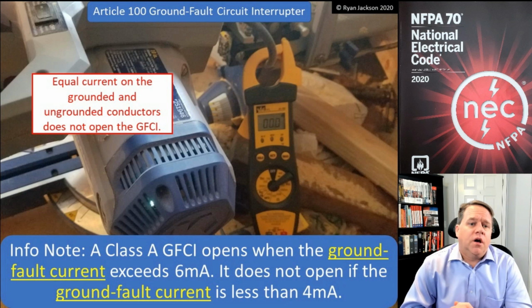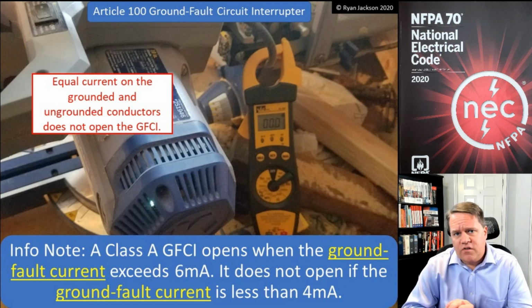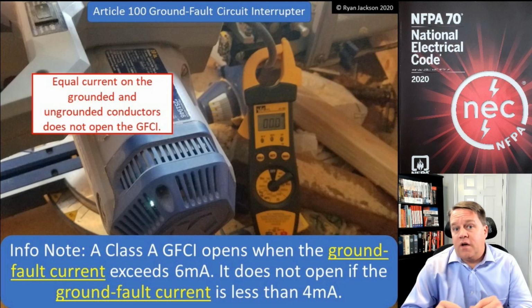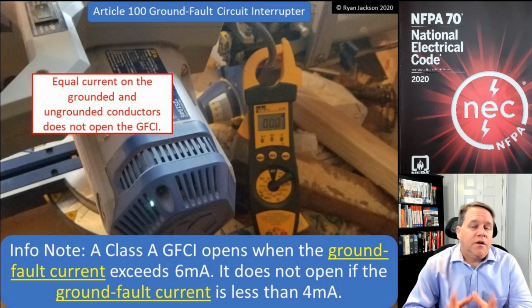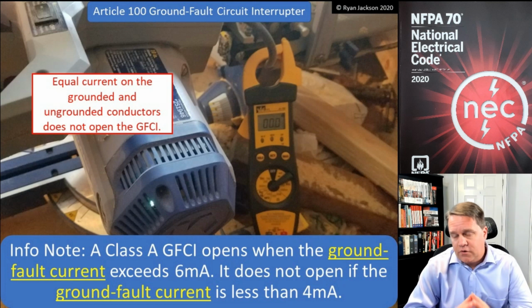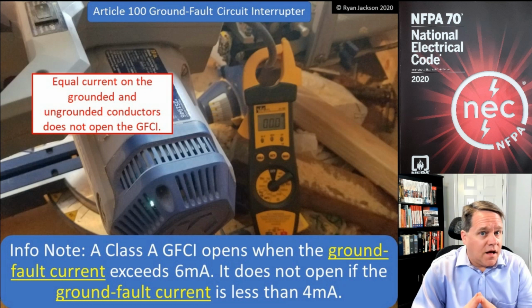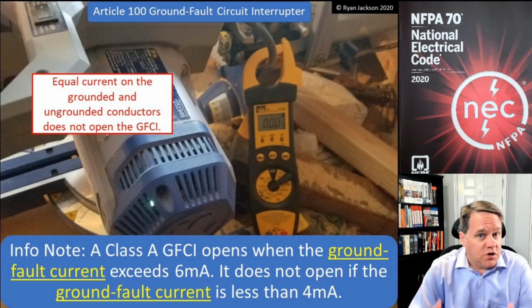So what am I trying to show here in the photograph? Well, the way a GFCI works is it monitors the current between the circuit conductors. That's true whether it's a 120 volt circuit or a 240 volt circuit or a three-phase circuit. It doesn't matter. It measures the difference in current between the circuit conductors. So what do I mean by the circuit conductors? The ungrounded conductors and the grounded or neutral conductor if the circuit uses one.